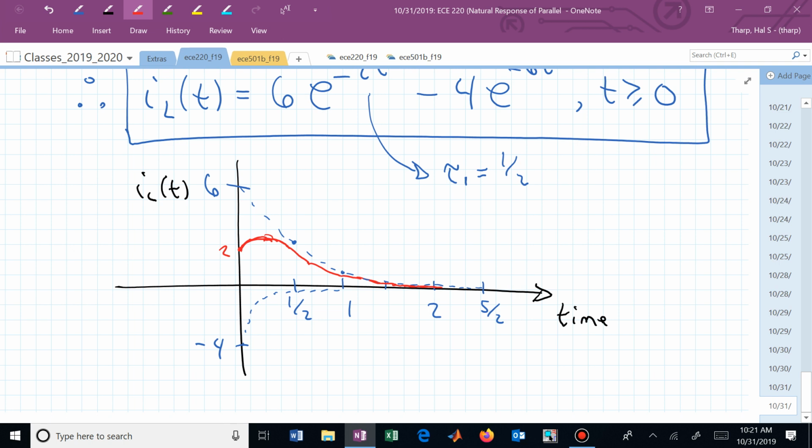for this circuit, a parallel RLC circuit. It's an overdamped solution. The next one that we're going to talk about is underdamped. It's now going to be an exponential decaying envelope, and inside that's going to be this cosine waveform. This cosine waveform will exponentially collapse.